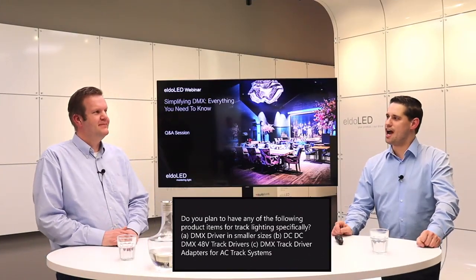No. And there are 10, 20 different brands available. Next to that, you can also do the addressing on those units, because there is RDM in the protocol as well, to set the DMX addresses with that same diagnostic tool. So investing in such a tool when you are doing DMX projects makes a lot of sense. It's mandatory. If you don't have such a tool, don't complain when something is not working. You just need that tool. If you buy that tool, you need it to be able to do it correctly. And if everything goes well from the start, you might never need it. But once there is an issue, that device pays for itself. Okay. Well, you cannot do everything at once.